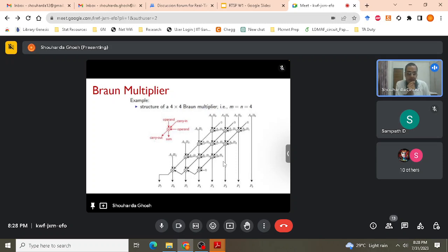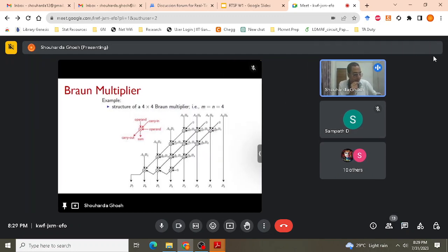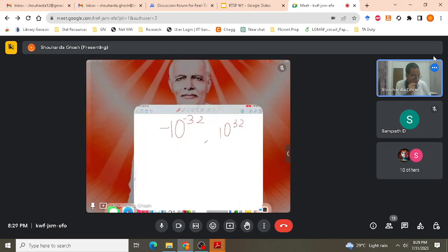Okay, so when you are adding two bits over here, rather than a full adder, we call it a half adder. So here we are using 4 half adders, and there are a total of 1, 2, 3, there are 3 in each row, and there are 4 such rows, so there are a total of 12. Let me write it down over here. There are 12 adders, out of which there are 4 adders which have a 0 input. The input 0 being given, so there are correspondingly 4 half adders, and then the rest 8 full adders.